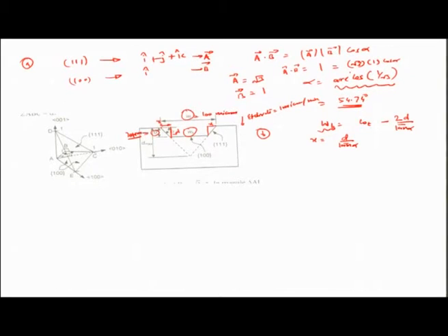So in this particular case, WB would be equal to 100 minus twice 20, which is the amount of vertical etching which has happened in the time duration of 20 minutes, divided by tan of 54.74 degrees, and therefore this particular number WB comes out in this case equal to, this being equal to root of 2, 100 minus root of 2 into 20, that's approximately 71.7 microns.